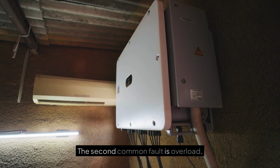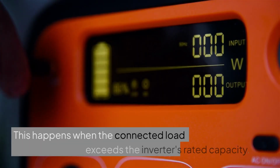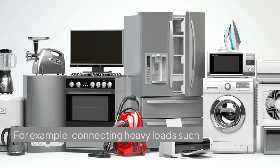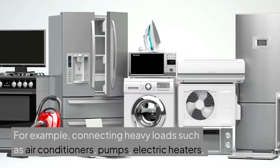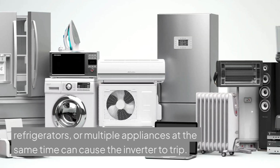2. Overload fault. The second common fault is overload. This happens when the connected load exceeds the inverter's rated capacity. For example, connecting heavy loads such as air conditioners, pumps, electric heaters, refrigerators, or multiple appliances at the same time can cause the inverter to trip.